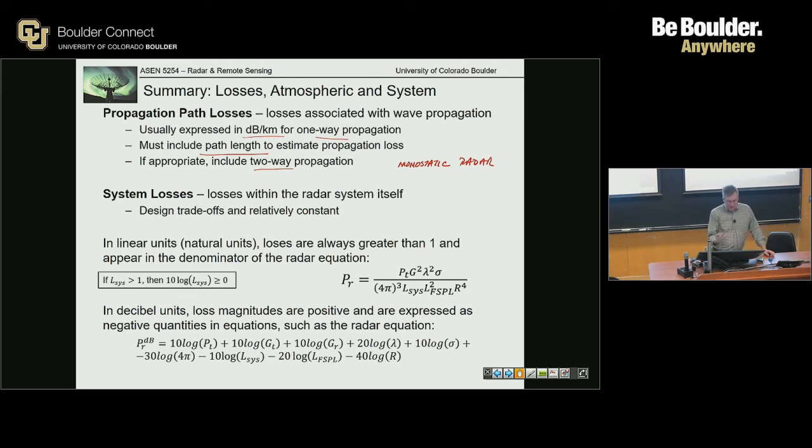So for system losses, where you have a cable or something that's inside your system, you would characterize it in the assembly process: calculate the loss, add up the components, disconnect cables, send a signal through, calculate the loss, and go part by part to characterize the system. Calibrate it. Measure with the VNA.